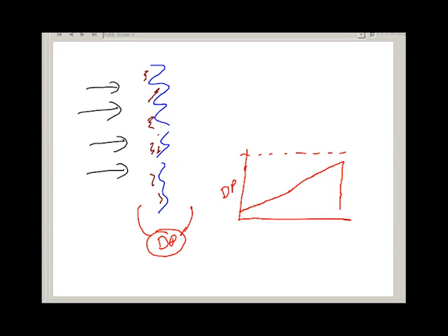If a hole blows through the filter, and that's quite a common thing to occur if the filter's getting blocked up, now there's no DP across it. If there's no DP across it, then the person looking after the filters says, well, I don't need to change them. Of course, that's silly. He very much needs to change it.